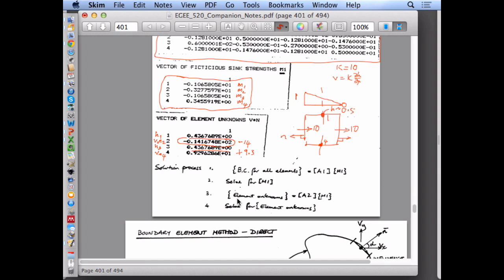And you do it in the same 2 steps. You satisfy the distribution of cracks opening in normal mode and in shear. You end up for n boundary elements with 2n equations, one for shear and normal displacements, and for boundary conditions in terms of maybe shear stresses and normal stresses. You solve for the distribution of those little cracks, the strengths of those cracks, how open they are and how sheared they are, and then you do the reverse substitution to be able to impose those known strengths, but use the functions that instead of giving you the stress condition at some location, give maybe the displacement condition. And so they fit into that mode.